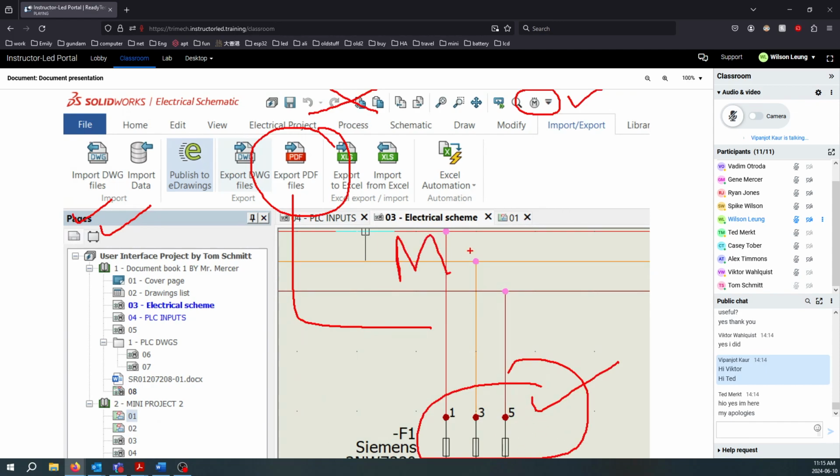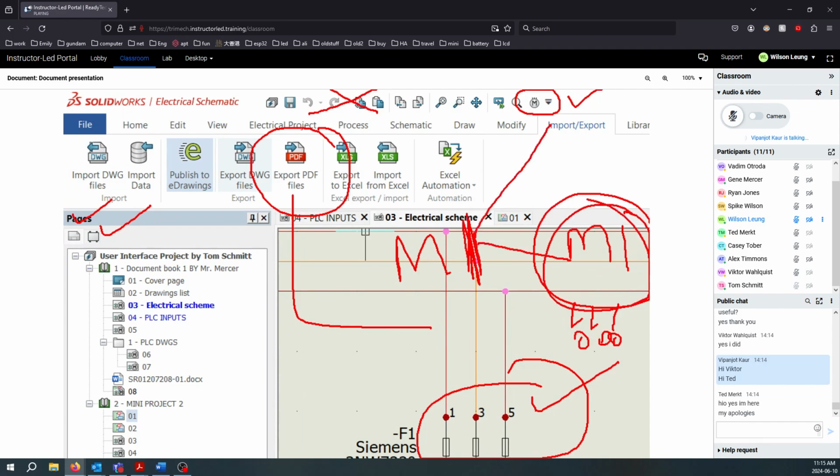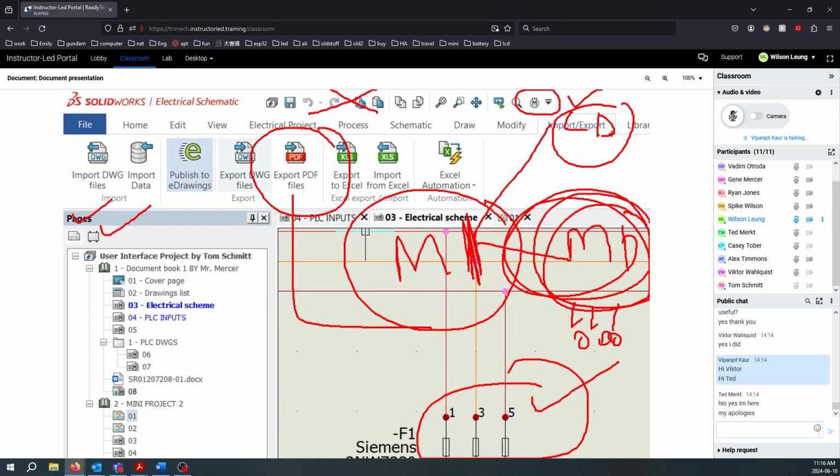So let's say I have a motor component M1. If I showed a motor picture that I clicked with my camera, on a line diagram symbol, and then I have an actual motor schematic symbol showing the detailed schematics. So now when I click on the symbol on the schematic, it will jump to the line diagram page motor symbol. If I click on the line diagram motor symbol, it will jump to the motor schematic symbol. So if one parent component has multiple pictures shown, multiple diagrams shown, multiple symbols shown, we can jump from one to the other and vice versa, right? So all these hyperlinking bookmarks will be available in the PDF.